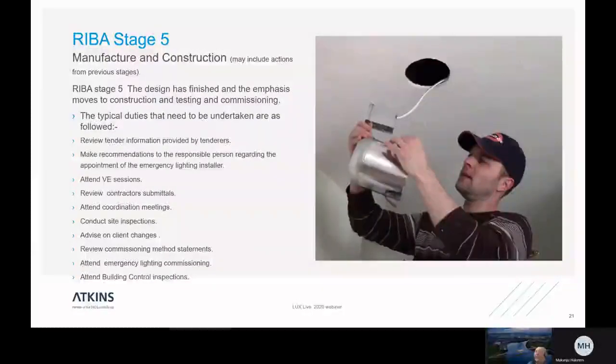If they have come in with an alternative, then your emergency lighting design may well be compromised because the alternatives that they have chosen do not have the spacing to height ratios and the output that is necessary for the job. Each LED fitting is fundamentally different from manufacturer to manufacturer.